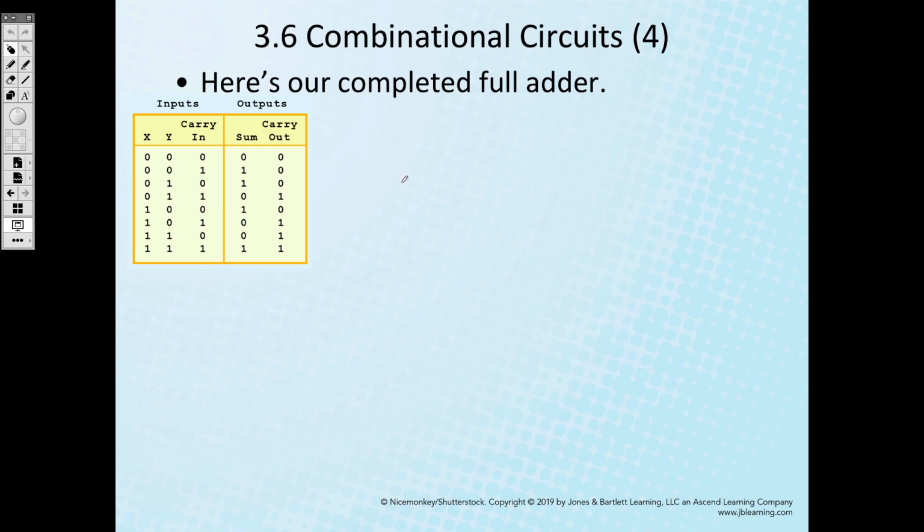So you can use a 3 variable K-map. So we have X and then Y and C in. So we have a 3 variable K-map. 0, 1, 0, 0, 0, 1, 1, 1, 1, 0. And then let's construct a K-map for that. So for some part we have 0, 1, 1, 0. So 0, 1, 1, 0. Keep in mind that order. 1, 0, 0, 1, 1, 0, 0, 1. That is the order. So this is for sum.